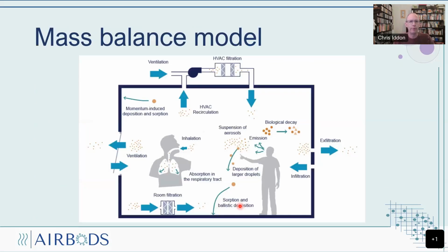First of all, we have a mass balance model, which enables us to establish what an inhaled dose might be by calculating the concentration of a pollutant in a space, and in this case, it's a virus. So the virus will be emitted into the space from an infected individual through aerosols, through talking and breathing.